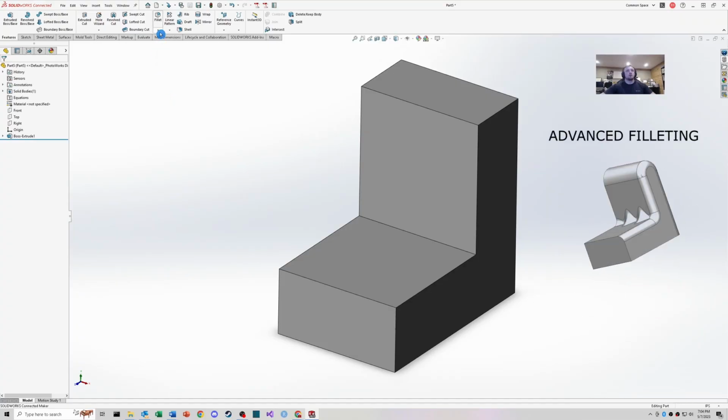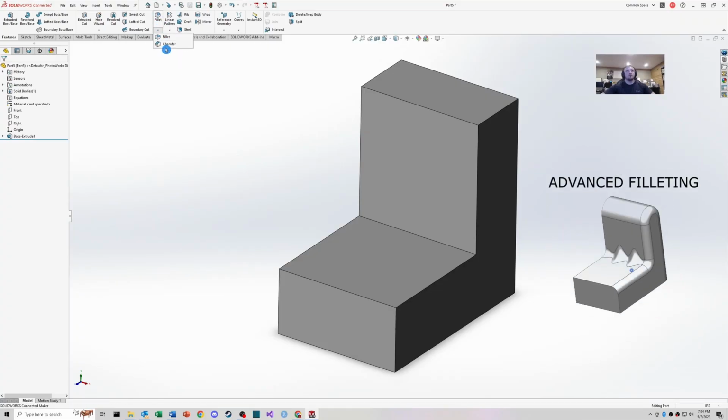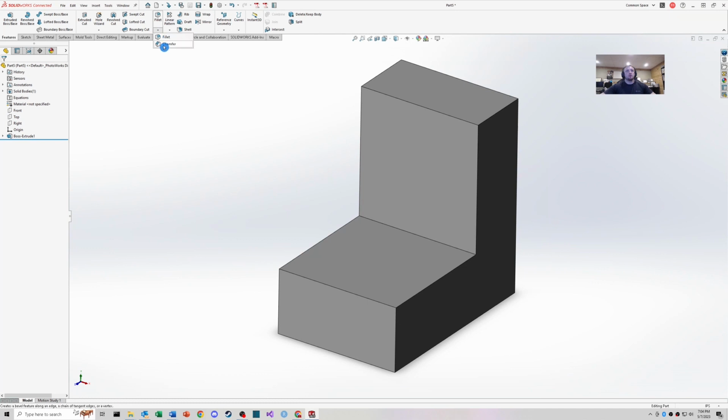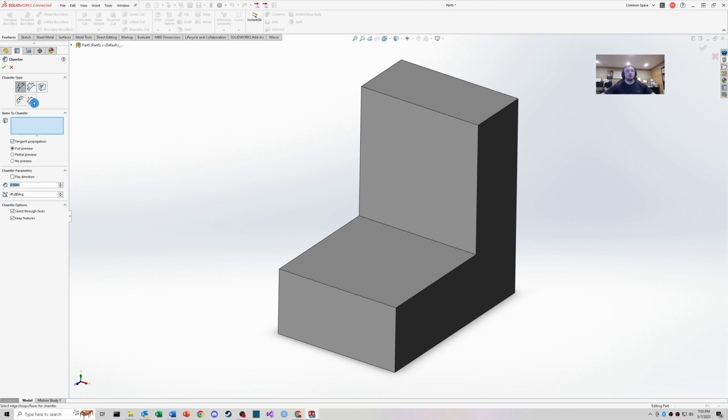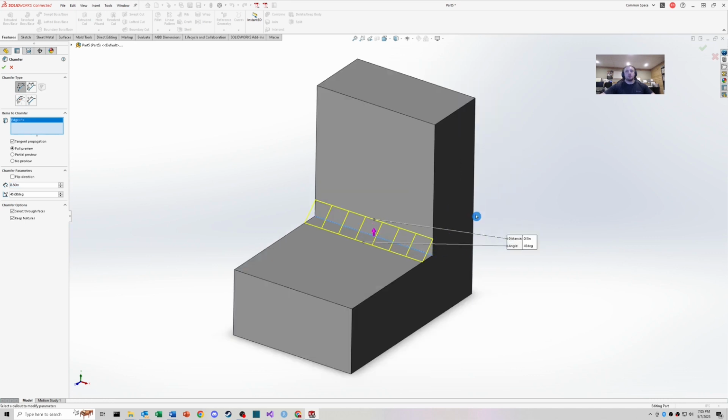All right, let's take a little deeper dive into fillet features. Before we talk more about fillets, I didn't point out the chamfer feature last time, which works very much like the fillet feature or the chamfer feature that we saw in sketches. If I want to create a simple chamfer, I can just select an edge like that, or I can select a face to grab all the edges of that face. There are also some different chamfer types we can define. By default, it's set up to be a distance and angle, so I can change my angle here, or my dimension to 1 inch like that.